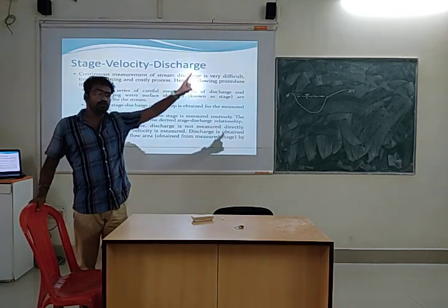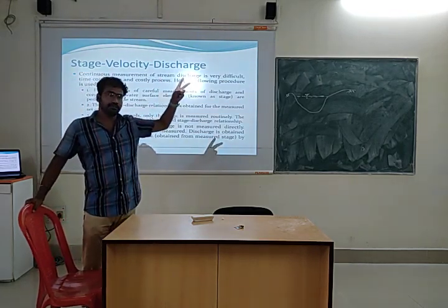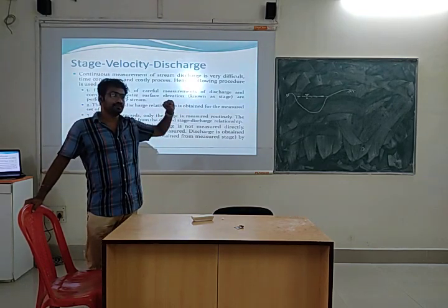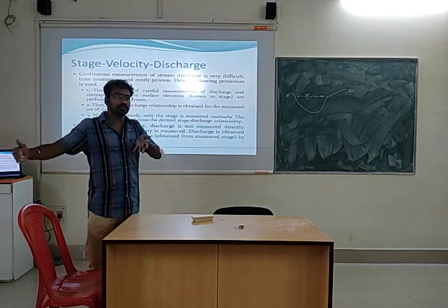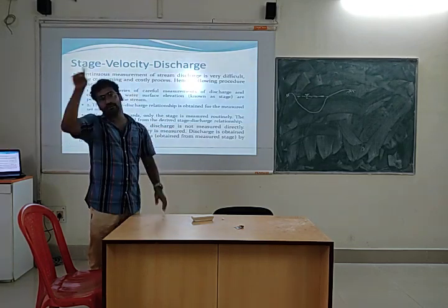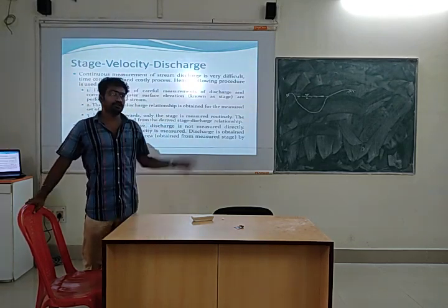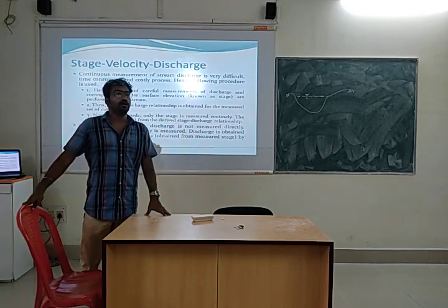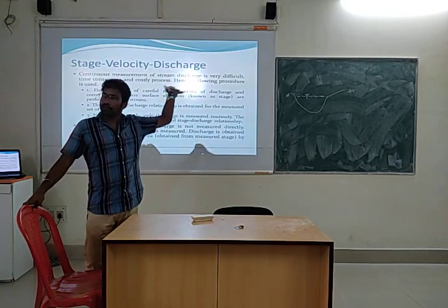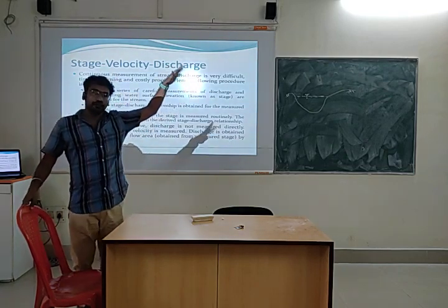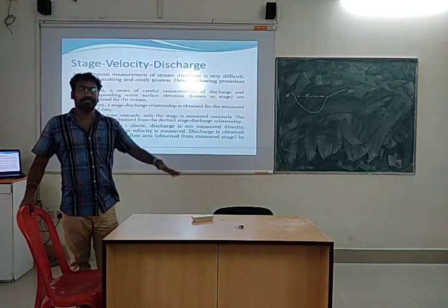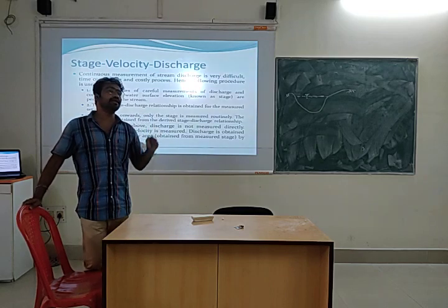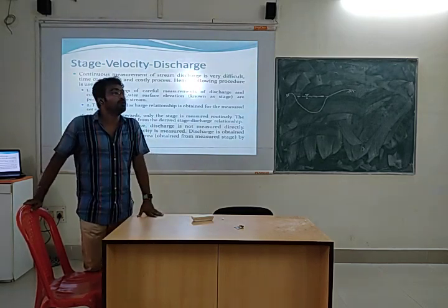So basically you have volume and velocity, right? That volume has two things: the length actually crossing per unit time, and the cross sectional area. Now that cross sectional area is dependent on the elevation, on the height of the water, and obviously the height of the water will not be the same every time. That is the main variable in stream flow.